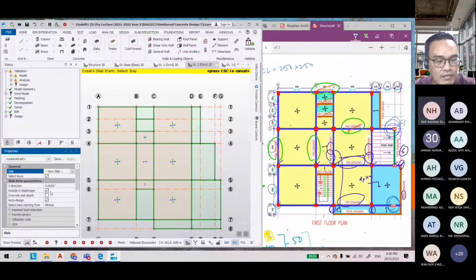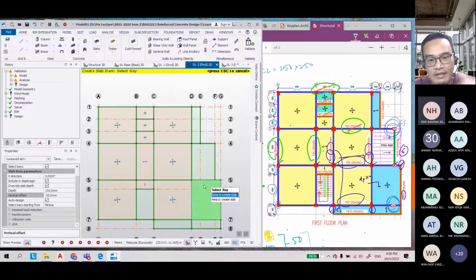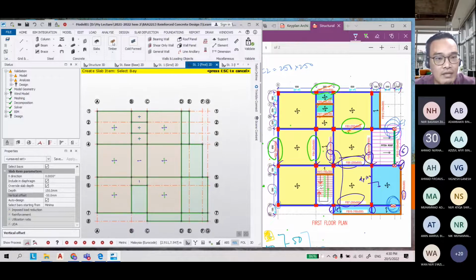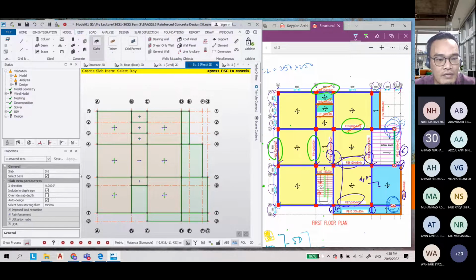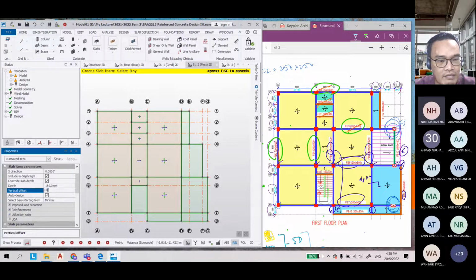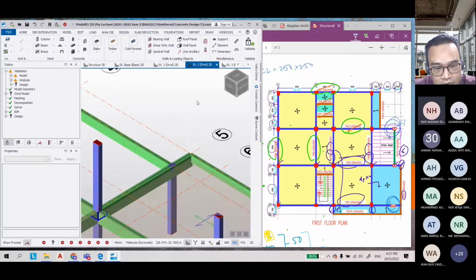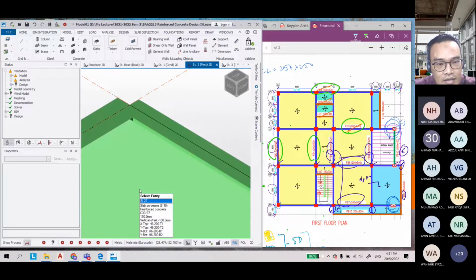Select the new slab, override, drop by -50. And it's two-way slab. And then this is for balcony. We have three or four types, so you check one by one. So select new slab, and then we do the two-way slab first, override by -100, and then do it here. We can check. So we can see that it's totally dropped now.